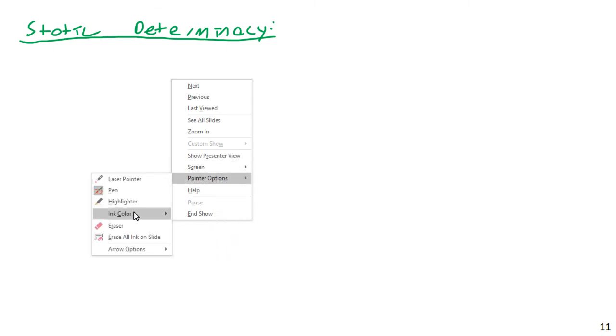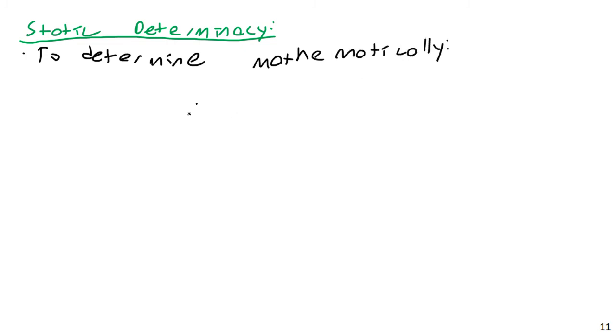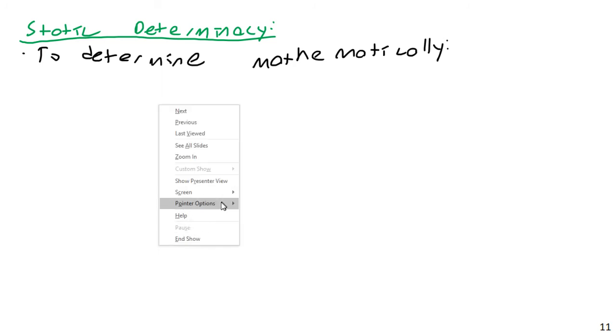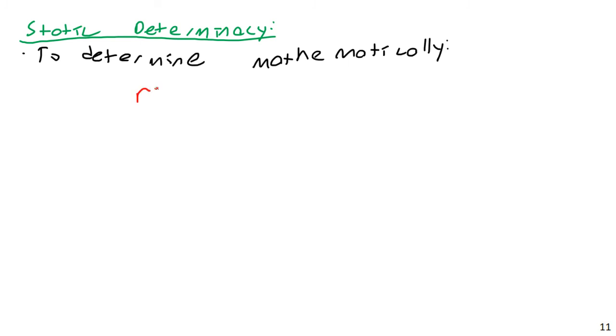Usually this is better than trying to just eyeball it. The equation is going to be exactly like this. If r is equal to 3n, it is statically determinate.